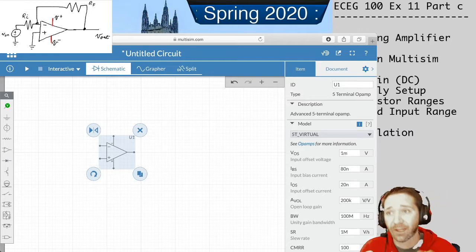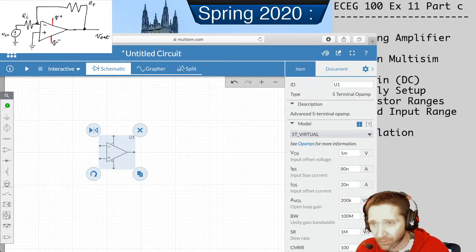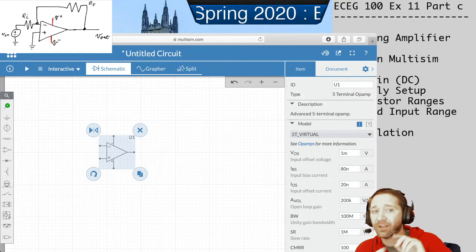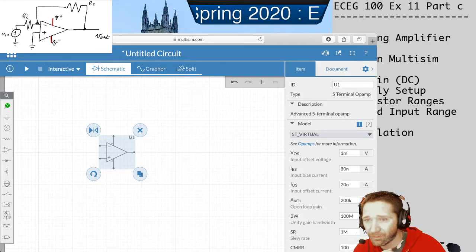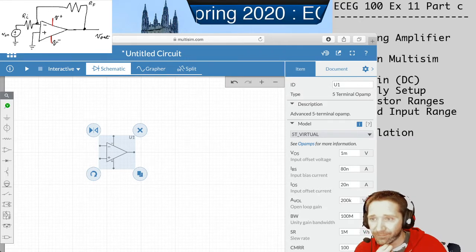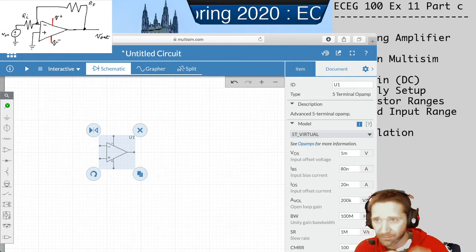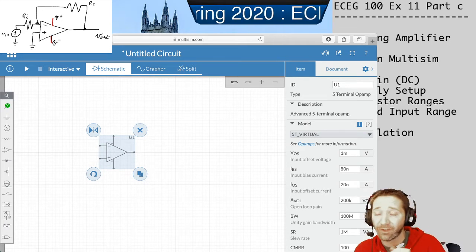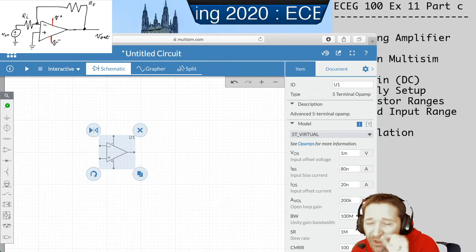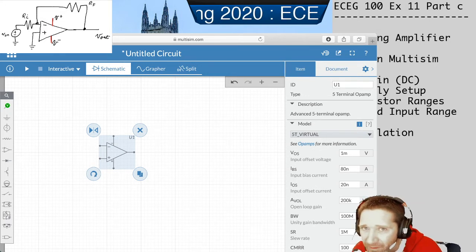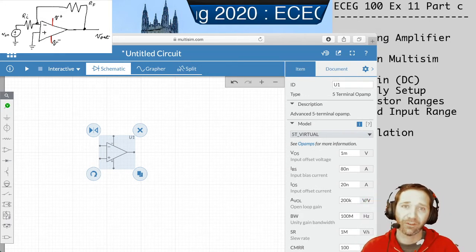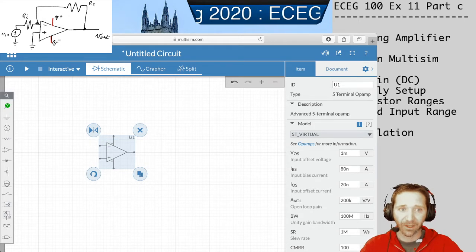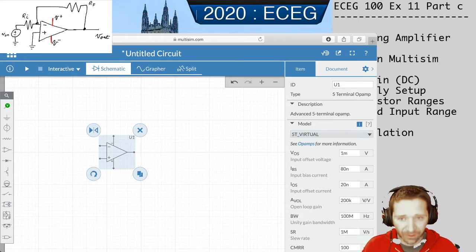If you look now at the power terminals, the terminals on the top and the bottom, you'll see that now the top terminal, the one at the top of the page, I can't point, my cursor won't capture, but at the top of the page you'll see that now there's a little bitty minus sign, and that little bitty minus sign is really important. So the minus sign means that it's expecting the negative supply voltage to be on the top and the positive on the bottom. That's just a little bit confusing.